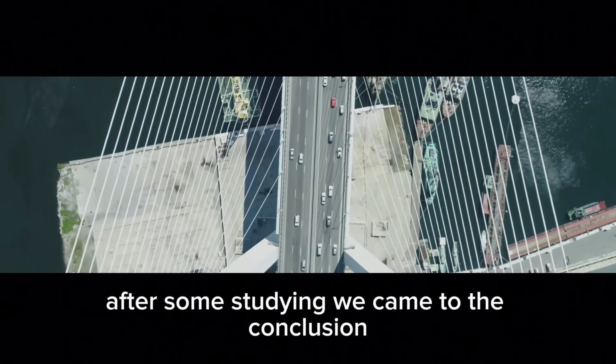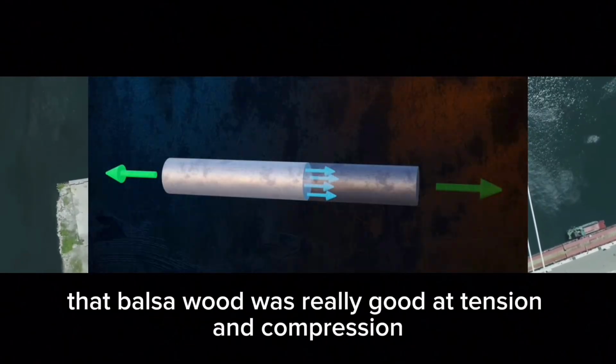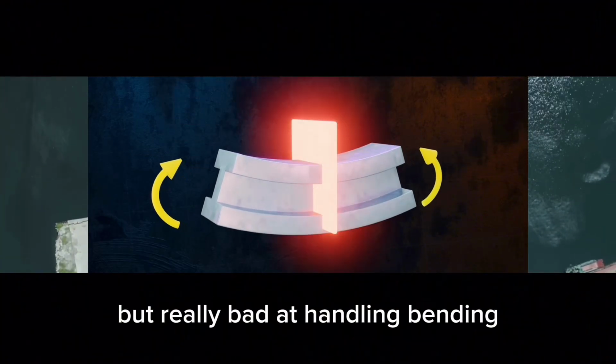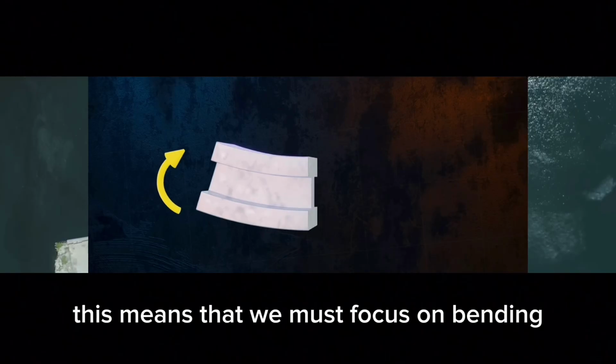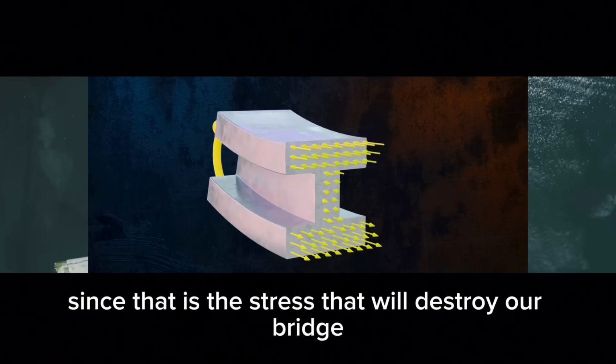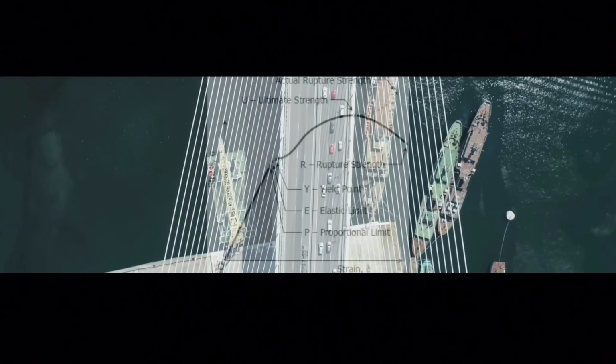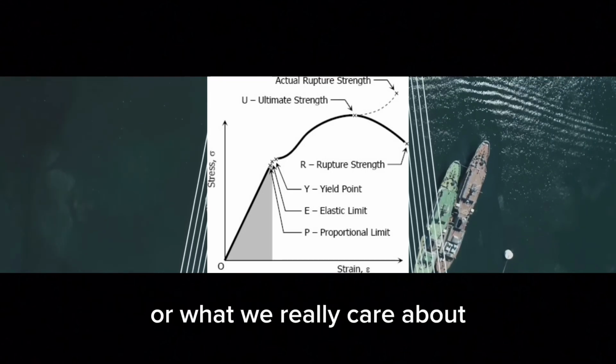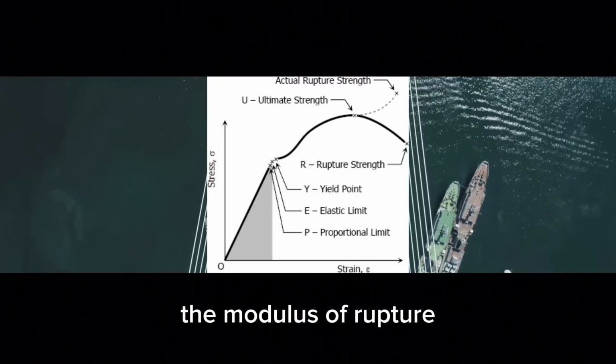After some studying, we came to the conclusion that balsa wood was really good at tension and compression, but really bad at handling bending. This means that we must focus on bending, since that is the stress that will destroy our bridge. How much something resists bending is flexural strength, or what we really care about, the modulus of rupture.